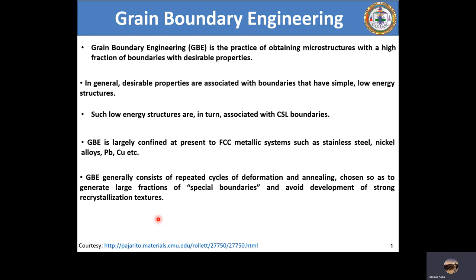Okay, in an equilibrium microstructure, I must say, those boundaries are getting preferentially corroded because of their high grain boundary energy, and especially if they are random high angle boundaries, they will have a higher tendency of getting etched or undergoing preferential corrosion as compared to a low energy boundary. So there is a reason why we are able to see the etched microstructure. But again, look at the problem of over etching, because if a microstructure has too many high angle boundaries, especially after the recrystallized condition, too much of high angle boundaries rather.